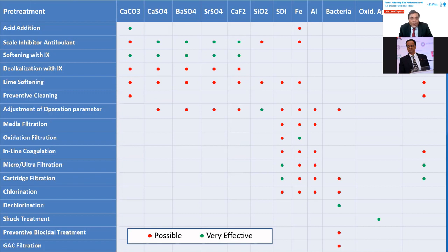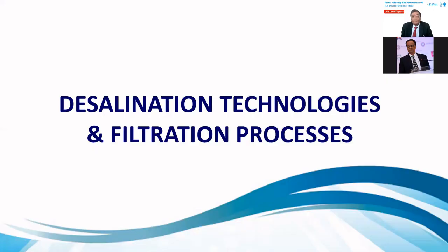of the RO plant. It means that when you don't have all these parameters which are mentioned at the top of the table, your designer cannot select an appropriate pre-treatment, and then later on you will be complaining to your supplier that they have not designed the system properly, or your RO plant is requiring cleaning frequently, and such types of problems you may face.